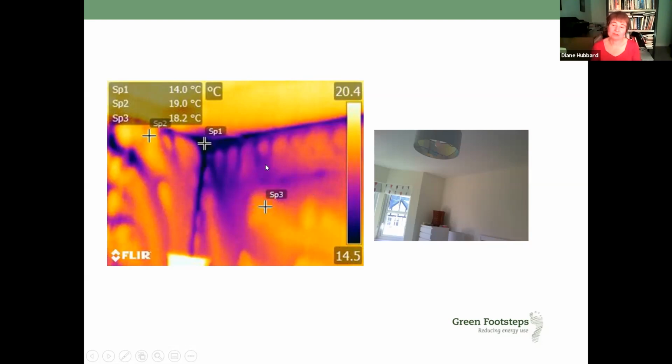And it's one of the pitfalls we need to try and avoid with retrofits, that we either use a continuous layer of adhesive all the way around the outside. There is still a risk, because the blockwork itself is air permeable, that you will get some thermal bypass. So the best idea, if you're going to use plasterboard, is to have a continuous layer of adhesive behind the plasterboard, or that the underlying wall is treated with, say, a paint-on airtightness layer. But that's a good example of showing what thermal bypass looks like.